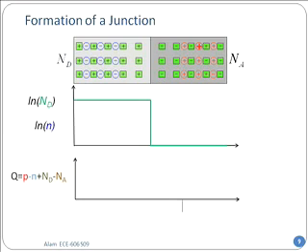Now, what about electrons from the left-hand side? Do you agree with this? The electron concentration was flat up to a point, and then it dropped because it has diffused away to the other side, and it has stayed at a low value on this side. What is the net charge?